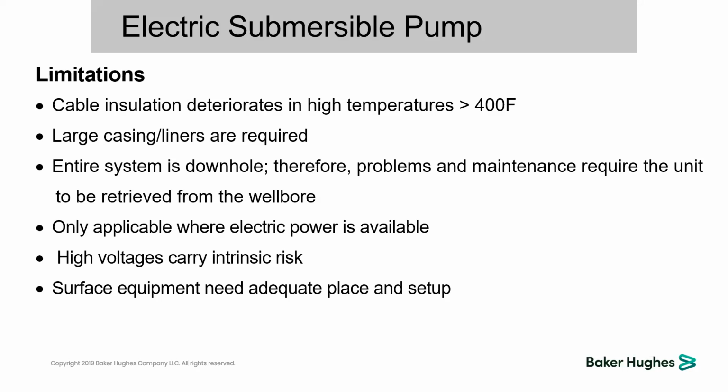ESP is only applicable when you have an electrical source. If you don't have an electric source, you cannot install ESP. And there is a risk of high voltage, which is one of the risks of ESP. So you have to get trained personnel in order to be qualified to deal with the existing risk. Also, the surface equipment, which we will go through, requires enough space to be set up, and that space might be a limitation on offshore fields, and you might change from one piece of equipment to another in order to fit with the existing offshore skid.